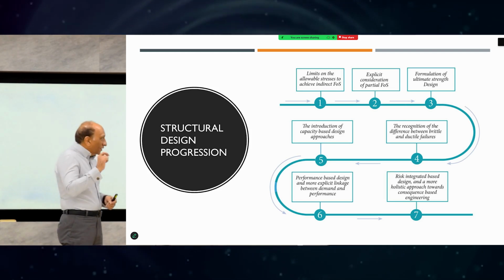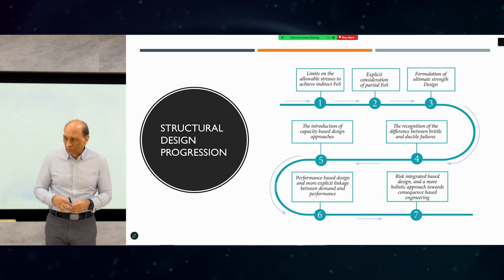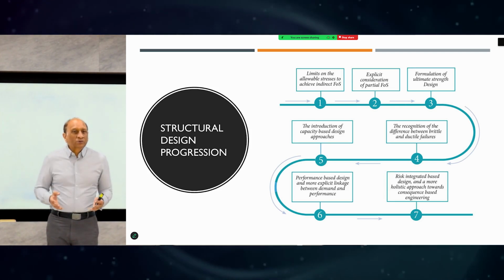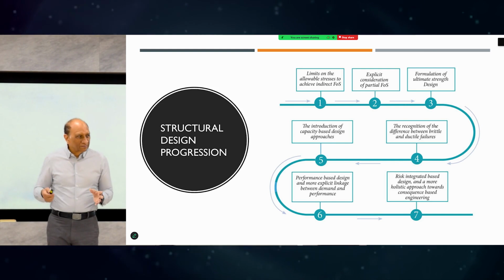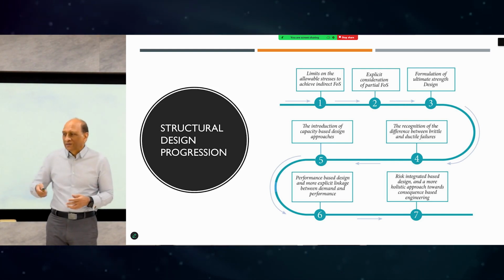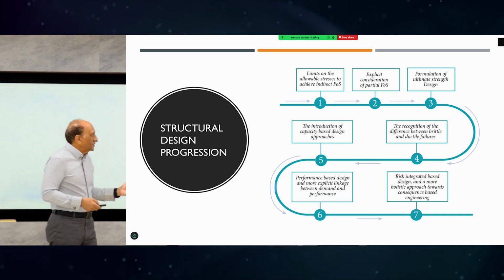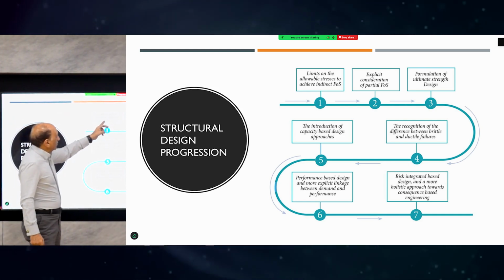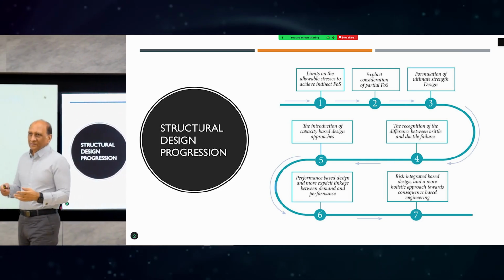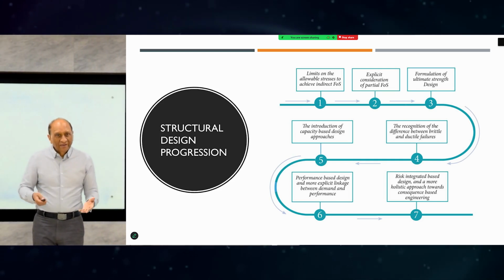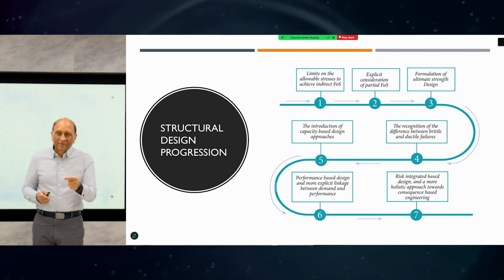And one of the reasons that worked at that time is steel. If it was reinforced concrete, they would not have been able to do, because steel, you can still use elastic design for most of the things. And they didn't have earthquake. So of course, it's highly over-designed, based on the current design standards. But the point is that it was only done on limit on allowable stress to achieve factor of safety, this level. So they just check the stresses, and based on those stresses, they make all their design. So stress check was the final check, that whether the steel stress is within limit, combined stress is within limit or not.